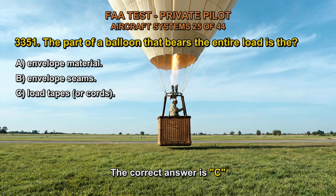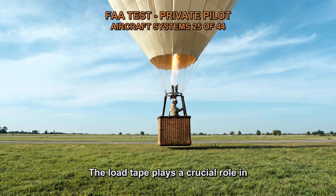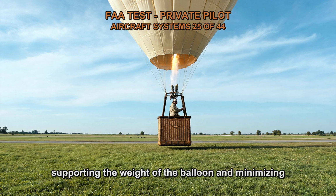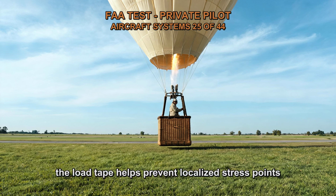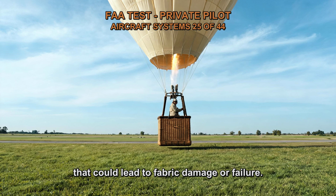The correct answer is C. The load tape plays a crucial role in supporting the weight of the balloon and minimizing the strain on the envelope fabric. By distributing the load evenly across the fabric, the load tape helps prevent localized stress points that could lead to fabric damage or failure.